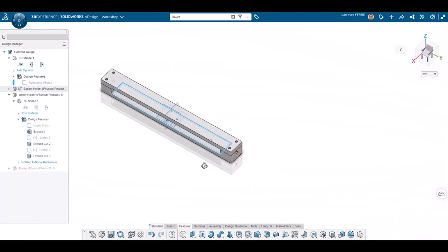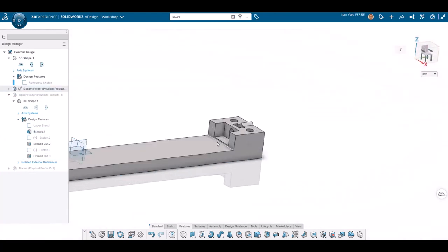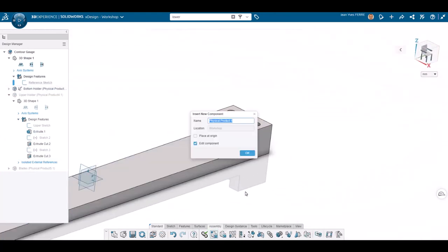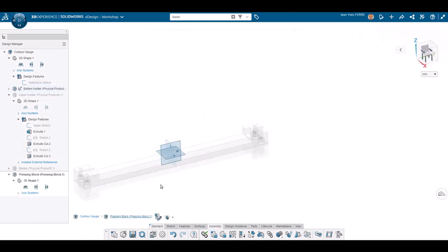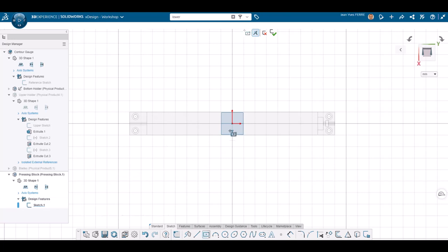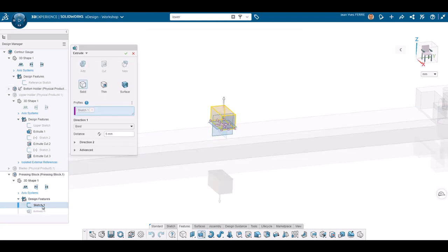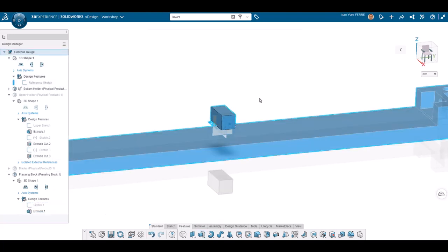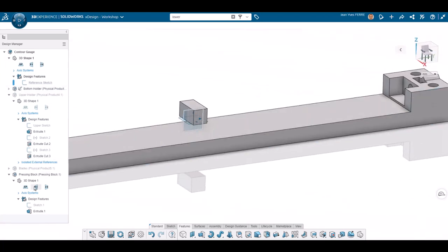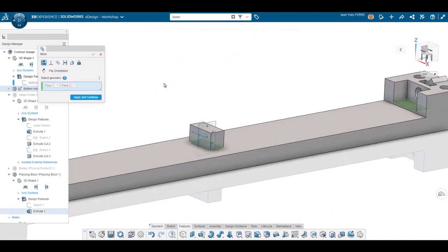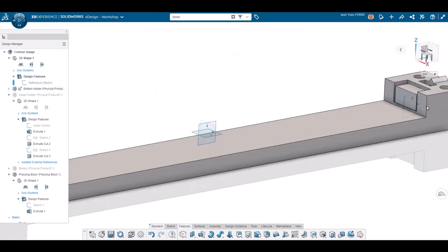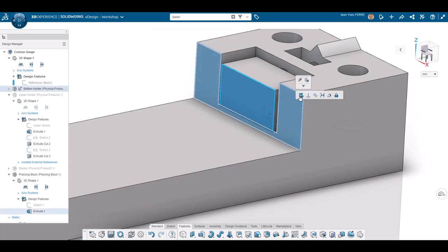Then I create a simple box between the blades and the clamping bolt so it can press on the blades without damaging them. Pressing a bolt on a plastic part can produce big efforts on a thin part like a blade. But on the other hand, if only the box is damaged, it is quick and easy to print and replace in a couple of minutes, faster than a blade. If I know that the block needs to be replaced often, I will print several blocks in advance next time. After adding a couple of constraints, the block is ready to use. As you can see, construction planes and model faces can be used for that.